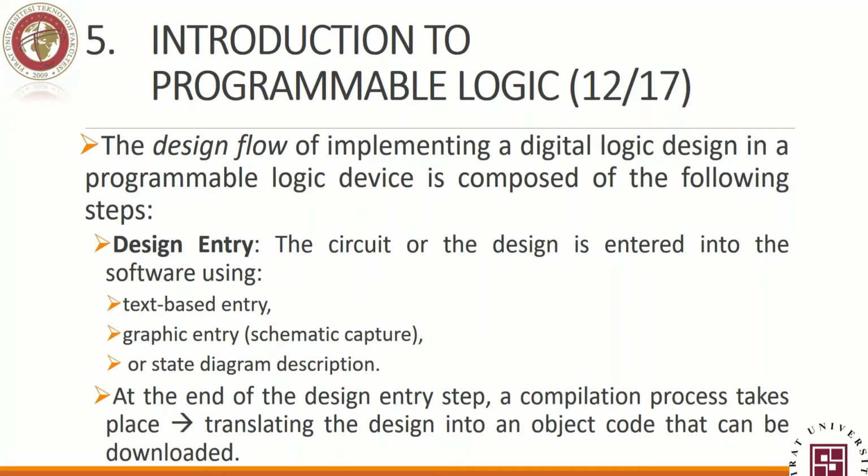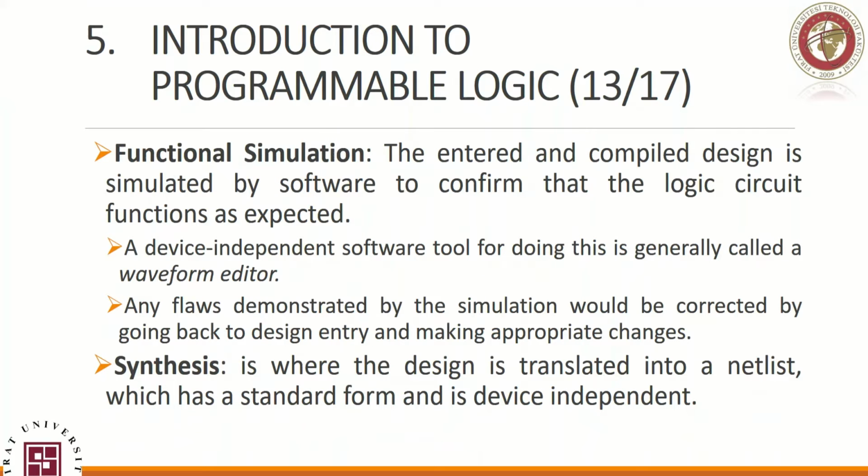Okay. Once we are done with our design, we need to program our PLD or FPGA based on it. We need to run it and see. So we need to compile the process that we created, and then we need to check if it is working or not. This is what we call functional simulation. In functional simulation, you simulate whatever you created before you download it to your device. Why? Because if you download it with any mistake or flaw, it wouldn't work. For that reason, we need functional simulation.